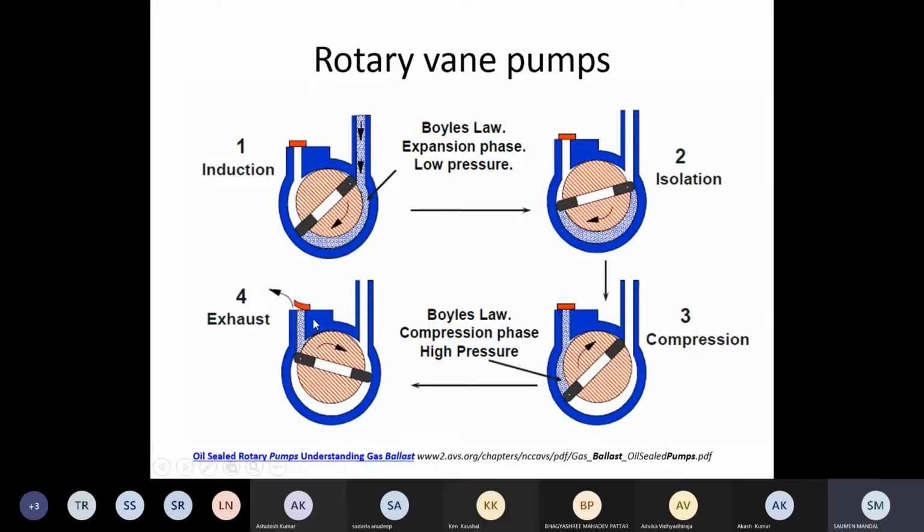Pressure will flow from a high pressure to a low pressure region. Just think, initially inside is atmosphere, then slowly it goes down. So you have to pump out the molecules from there itself. When this particular pressure becomes higher than atmosphere, the vent will open and it will go out immediately. This takes several rotations. In the first rotation it is easier to remove, because inside will be 1 atmosphere.